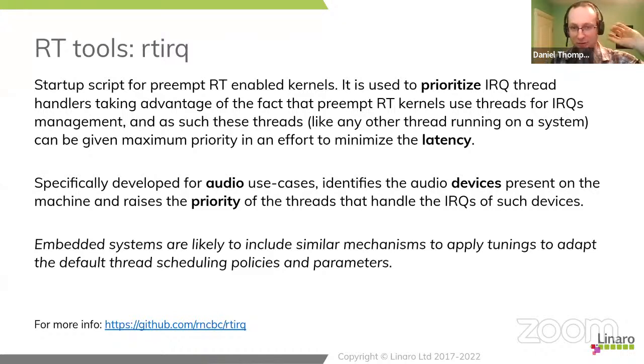And the idea behind that is then when the audio card delivers data, it's the highest priority thing in the system. Sitting below that is the DSP that gets triggered by the audio card having data to work on. And then you've got all your other interrupts. And that's a form of tuning. So you have the default tune, which is everything sits at SCHED_FIFO, runs at 50. You've got the default tune of things like ksoftirqd or your network kthreads. Again, they will come up with default values and their kthreads. And so after they have been established, you will have to reach in with a tuning tool like this. It's quite often a systemd service or something like that. That will go in and apply the tunings you want for your kernel and your application.